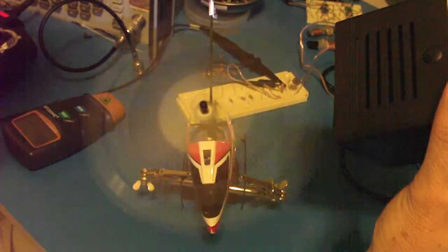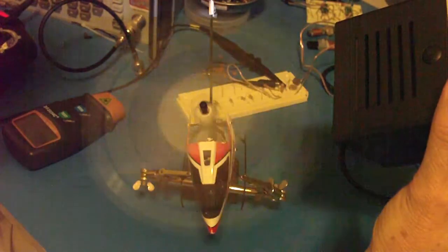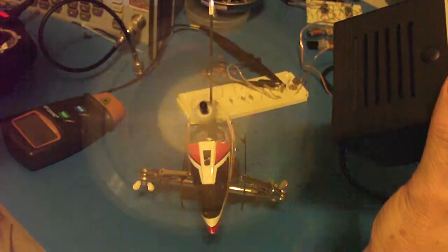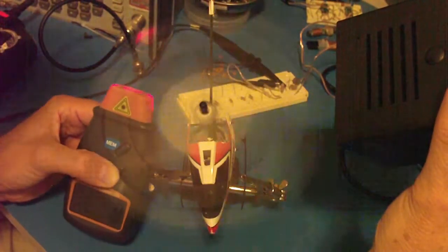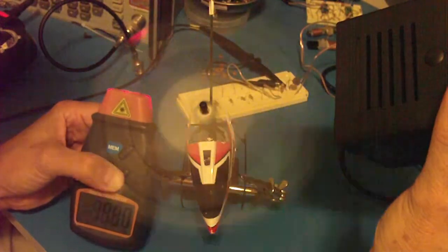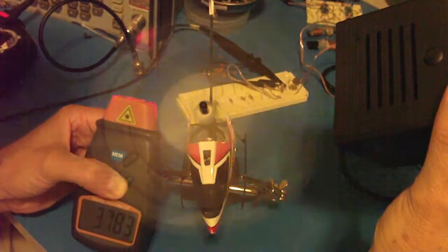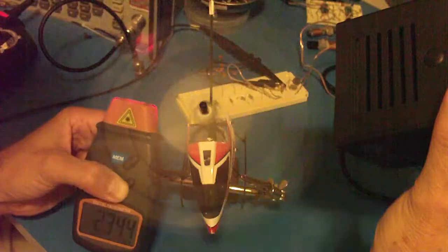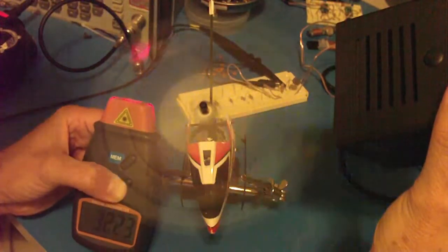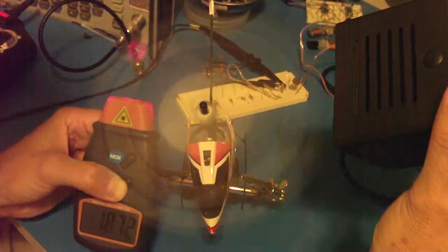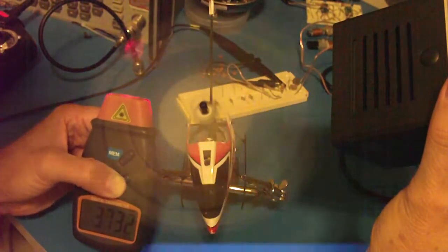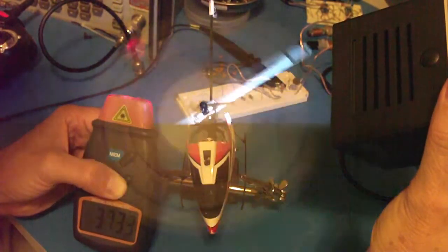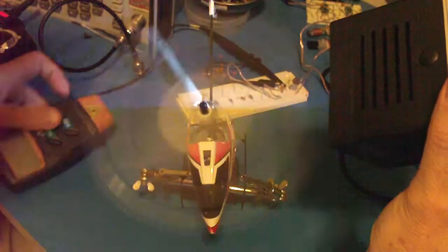So the next frequency that we're going to try is we're going to look for 1875 RPM, and it should have a reflector on each blade because there's 2.5 rotations per sample. And that should read 3750. It looks like it's rotating a little bit backwards, and that's why it says 3730 instead of 3750.